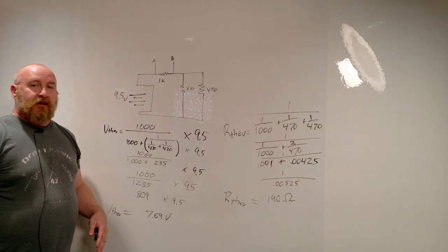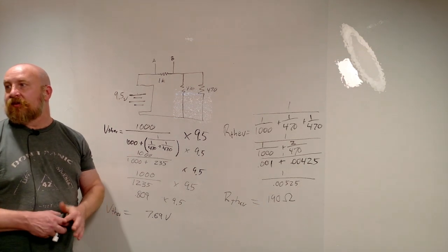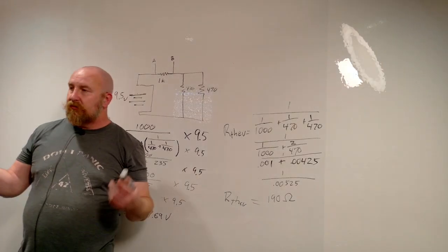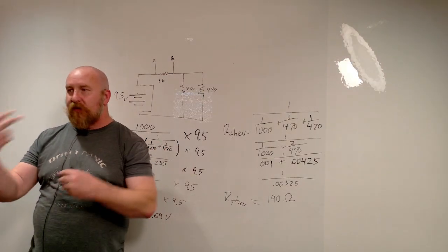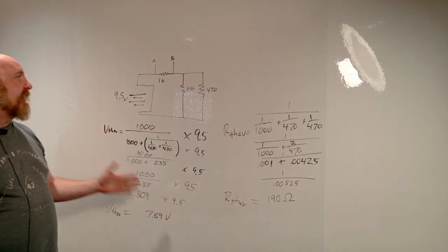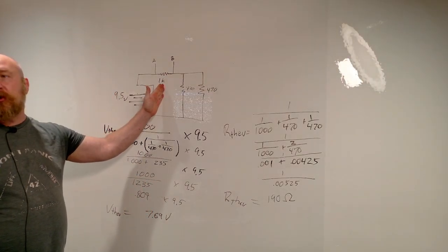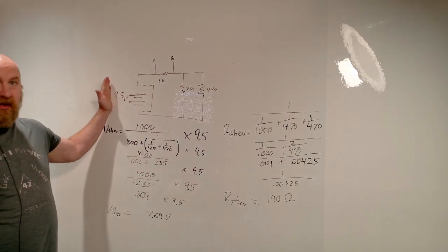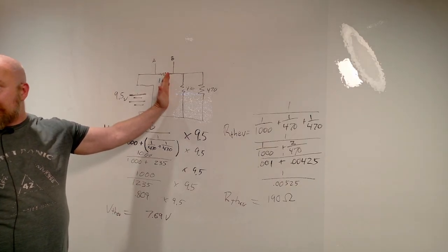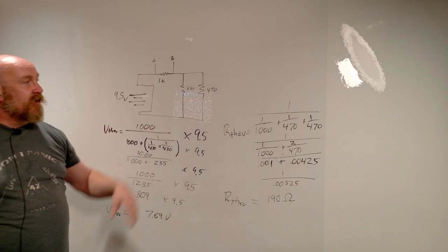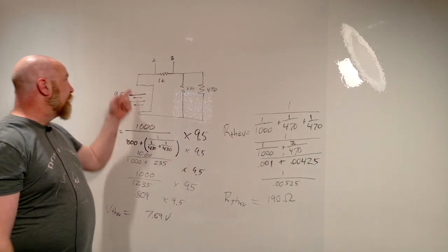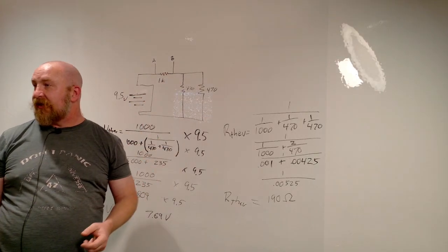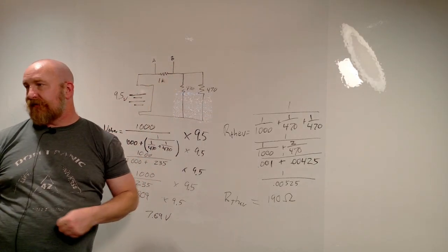Yeah, so check your calculations, check your equipment, if you're coming up with numbers and values that aren't making sense. So just keep in mind the simple flow of it. We need to find out what proportion of the total resistance this is and multiply that times the voltage. That's going to tell us our voltage drop. That's going to tell us what Vthev is. And then Rthev is just a matter of figuring out what's in series and what's in parallel and adding up the total resistance of that from this perspective.